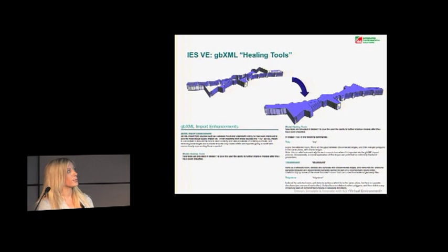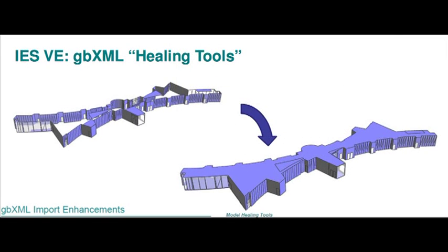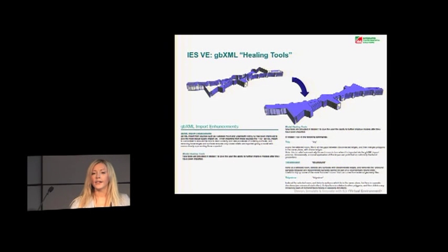One thing when you're looking at your model for import, you can see on this upper model all of this triangulation that's happening. This is something that we've worked to resolve a lot. Even though it's actually bounding and shutting your room, every time you add a surface in VE, you're adding time to your calculation. Even if you have a rectangular box or a cube with a lot of triangulation on it, the way the calculation engine works is that it's constantly checking each surface, and each one is just another reference point, a ping point that it bounces off during that analysis.